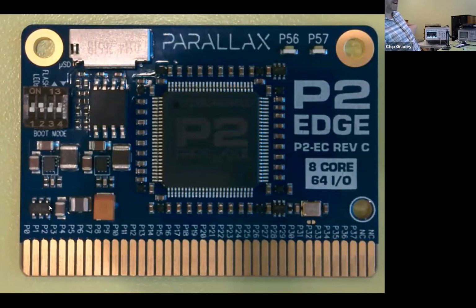Then when we come into this board here, we have a PMOS FET, which acts as a kind of a one-way, like a check valve, right? Like a diode, but there's no drop on it. So power comes in, this is like a 30 volt, 8 amp. It's amazing with these high conductions, these low RDS on values, that you can have a 30 volt, 8 amp part that's that big. Because when it turns on, it doesn't generate heat, it just passes the power through.